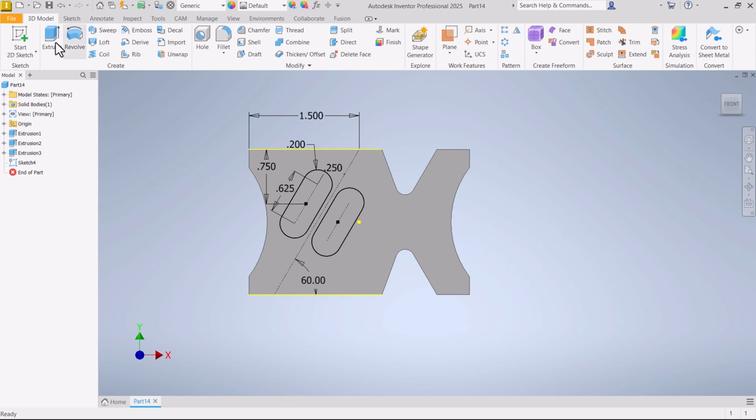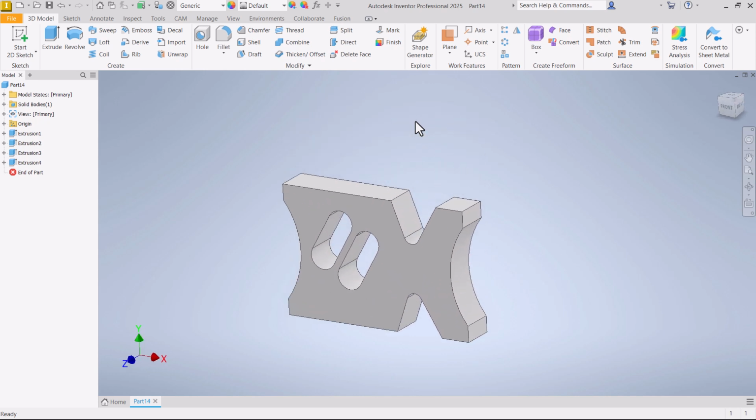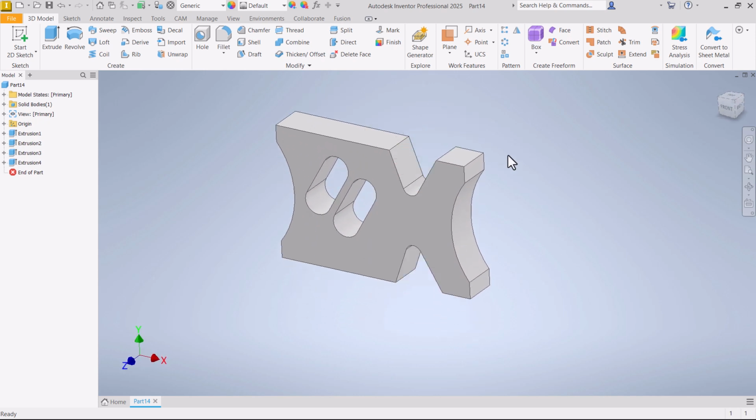So I think we'll stop with this one for now and just leave it right there. Finish this one out with an extrusion. I know it got a little messy at times. Sometimes that can happen with constraints. Sometimes you just got to hit undo a few times and back up. Decide whether you need to go ahead and apply a different constraint or a dimension to get things stabilized a little bit before you keep going with your dimensions.